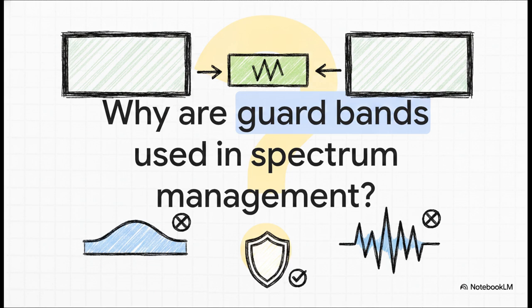The distractor options will try to trick you by claiming guard bands increase bandwidth or increase power. Totally false. Guard bands actually waste a chunk of usable bandwidth to act as a wall between adjacent FDM channels, intentionally sacrificing raw capacity just to keep the signal integrity intact.